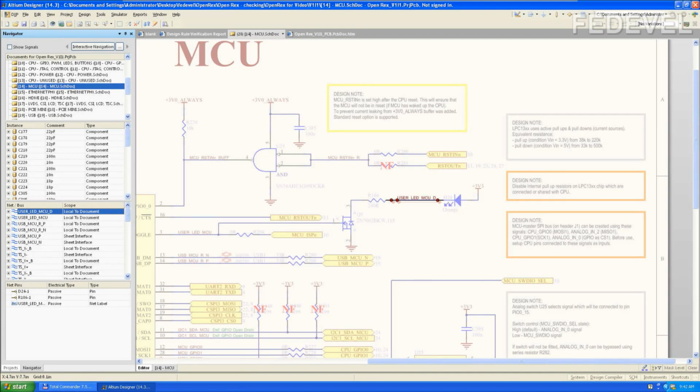Now, very important tip. Never ever order the signals in this window. It's because Altium can't remember how you set the ordering, and for example, if you switch off and switch on Altium, you will lose track of the signals which you have checked and which you still need to check. So just leave it as it is, never click here. Okay.